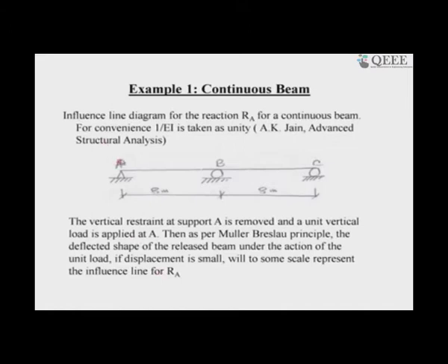That means, if a unit load moves from here to here, I release this redundant force. The redundant force is only a vertical restraint; I have not released the horizontal restraint, only the vertical restraint condition is released. So, it can go vertically up and down, but cannot move sideways. And then if I apply a unit load here, if the deformation is not excessive,